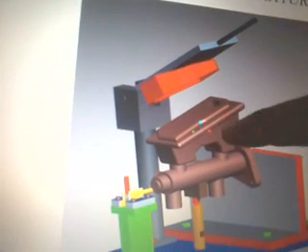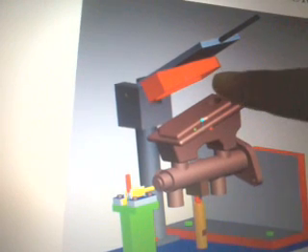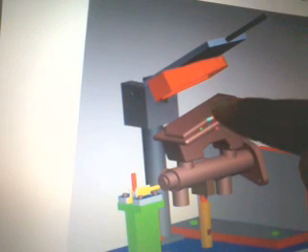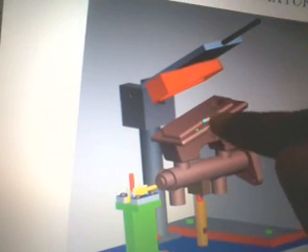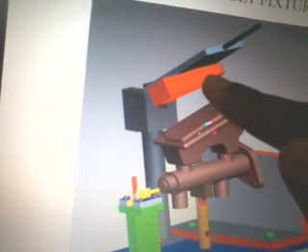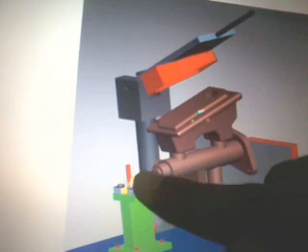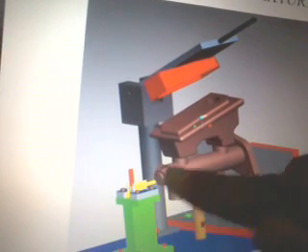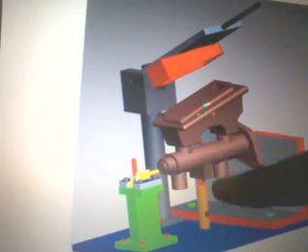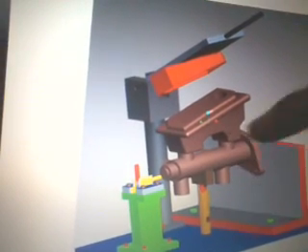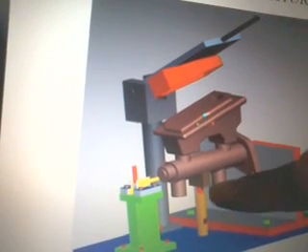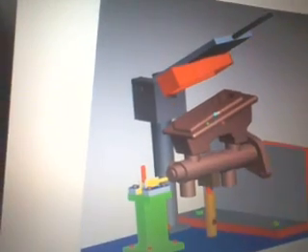When this happens, some force is generated. That force must not exceed a limited amount, because otherwise this reservoir tank will be damaged. This reservoir tank is made of nylon, so the material is selected as nylon. This is called a toggle clamp. It holds the master cylinder at one end, and the other end is mounted on the gusset plate. At the center of the master cylinder is a support pillar, which supports the master cylinder and transmits the whole weight throughout the assembly.